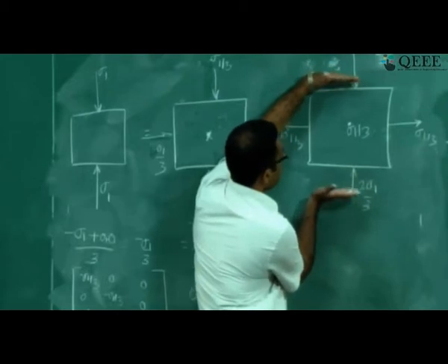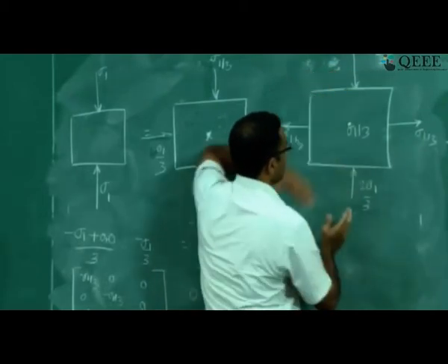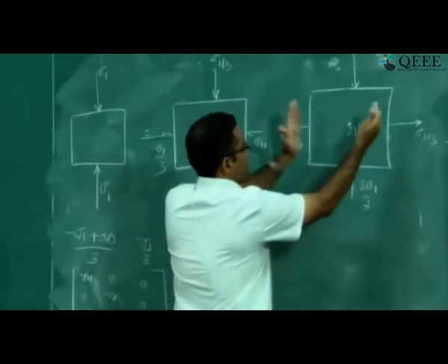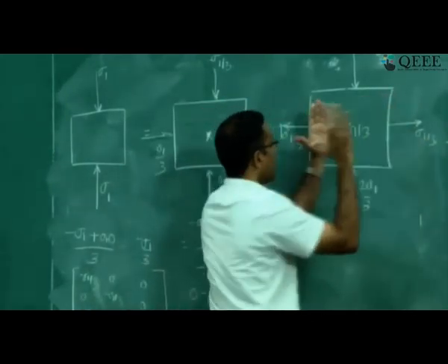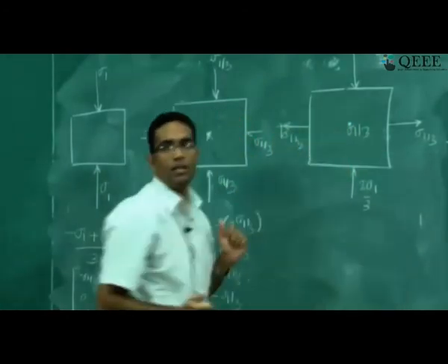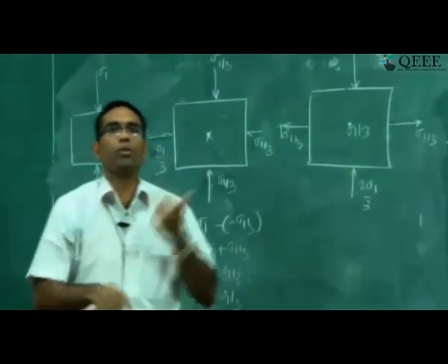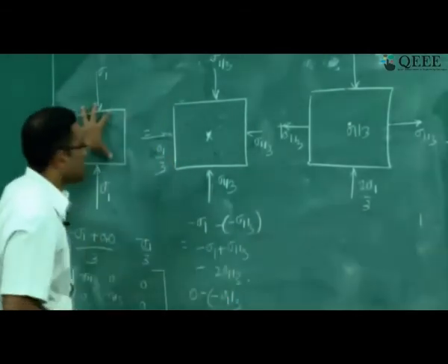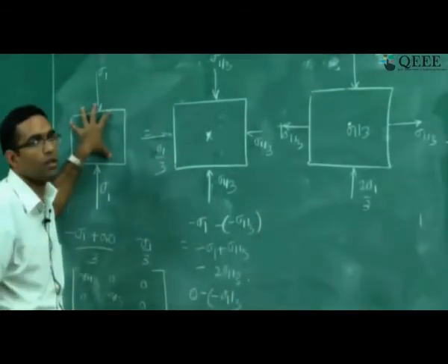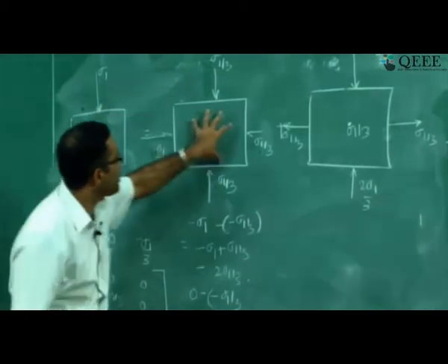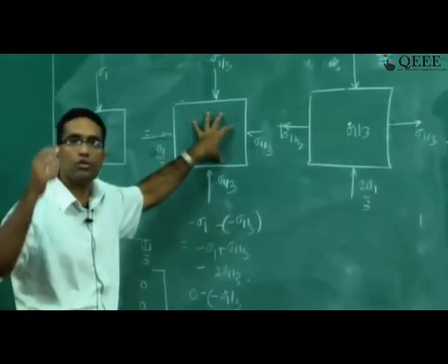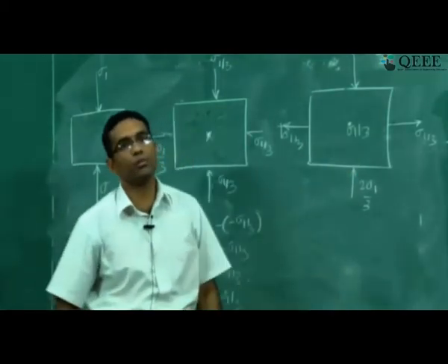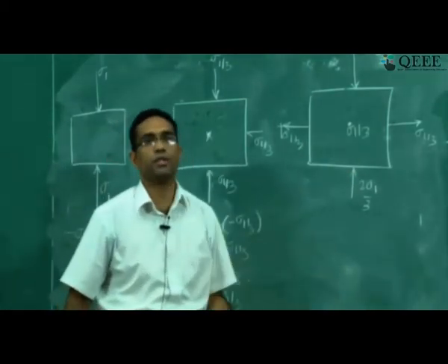The top and the bottom faces are being flattened out, whereas the side ones are being pulled apart. That means a cube is converted into a cuboid. There is going to be a change of shape, right? So in the total stress tensor at a particular point, the hydrostatic stress contributes to volume change, whereas the deviatoric stress contributes to shape change.